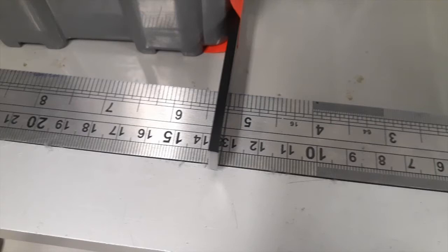Conclusively, we saw that we can measure some acceptable distances by using the terminal values of an LDR. Plus, we need to calibrate our constructed circuit each time the experimental environment changes, because each time we change anything slightly, we are going to obtain a different equation. That's all I would like to say about this project.